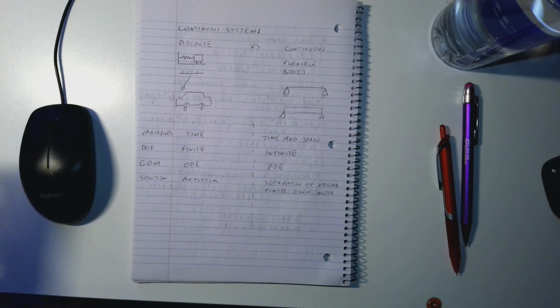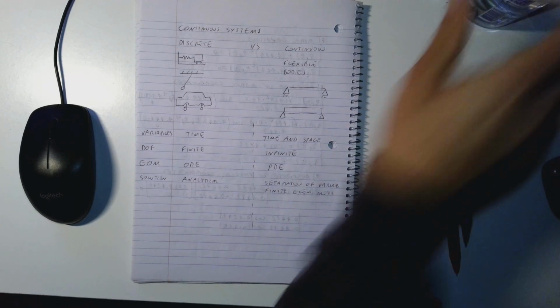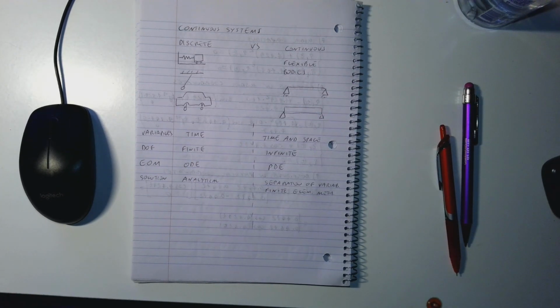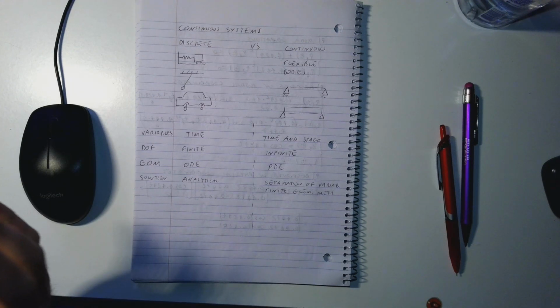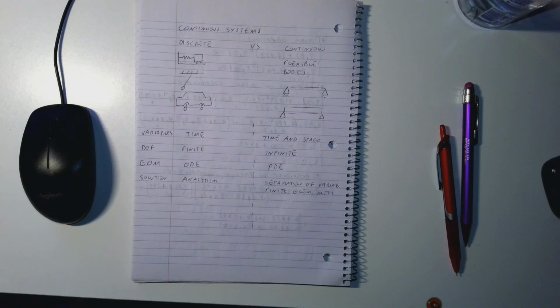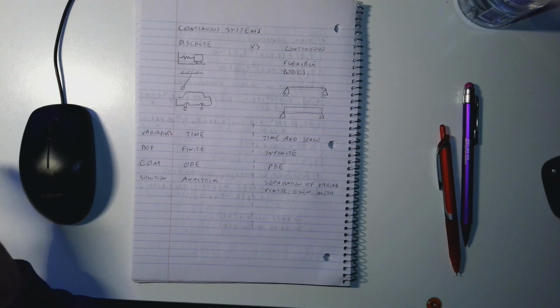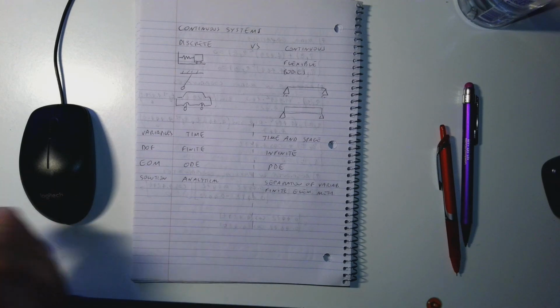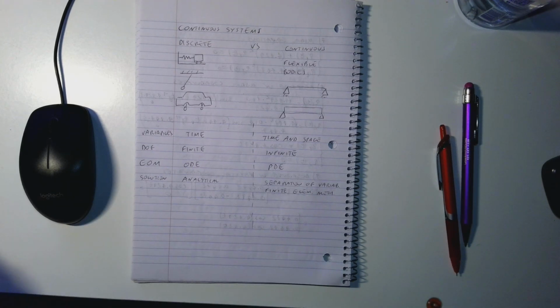So last time we talked at the beginning a little bit about the transition between 2 degrees of freedom and multiple degree of freedom systems. We said that the transition in this case is very easy. The only difference between a 2 degree of freedom system and a system with more than 2 degrees of freedom is the size of the matrices. If we have a system with 3 degrees of freedom, instead of having a stiffness matrix and mass matrix that are 2 by 2, we will have matrices that are 3 by 3.